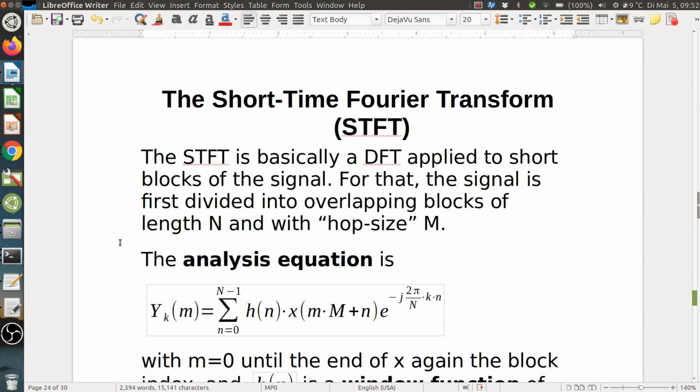So this is actually one easy way to do the inverse Z transform by inspection. You can just look at the poles, and you know that each pole corresponds to an exponential decaying function. Or if this pole is outside the unit circle, then it corresponds to an exponential increasing function.